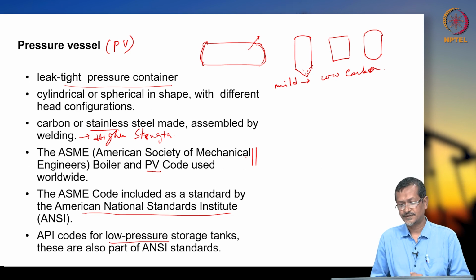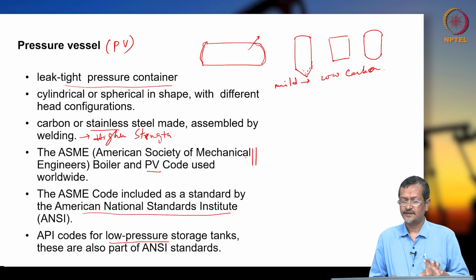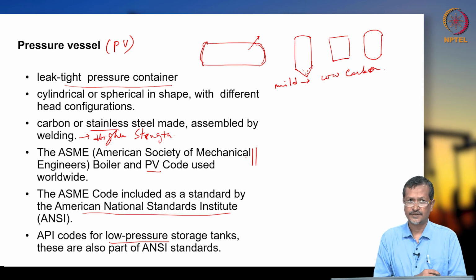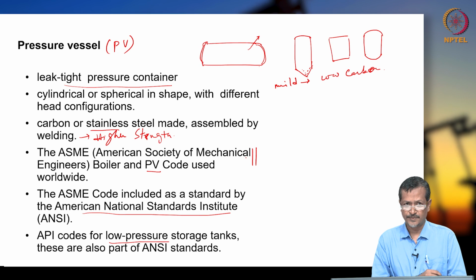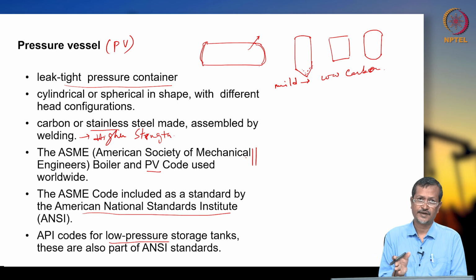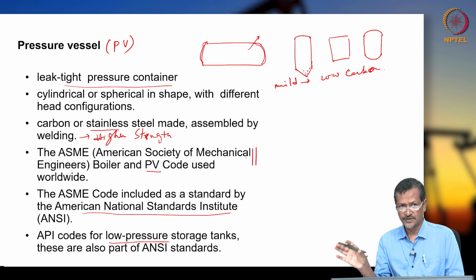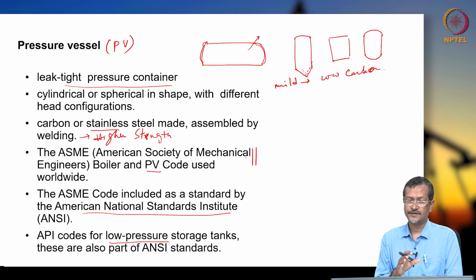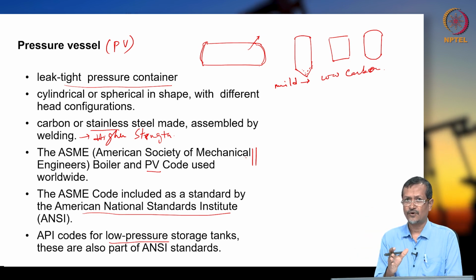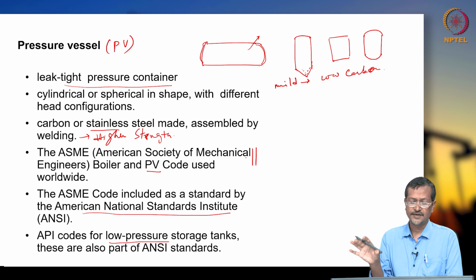And whenever you are buying a pressure vessel, some company is saying we are following the ASME standard, and those are standard pressure vessels, but there will be some non-standard pressure vessels also available. In that case you have to check their design, everything, because non-standard means they are not following the code, but they may be safe, they are using some specific material for that. That's why they cannot use the American specific code, because ASME will say okay, use this type of material for this thickness, for this pressure, this fluid. But let's say for a specific application you are using a certain chemical where ASME does not say anything. In that case that will be a non-standard code, non-standard design. So in that case you have to check their calculation so that things will be safe.